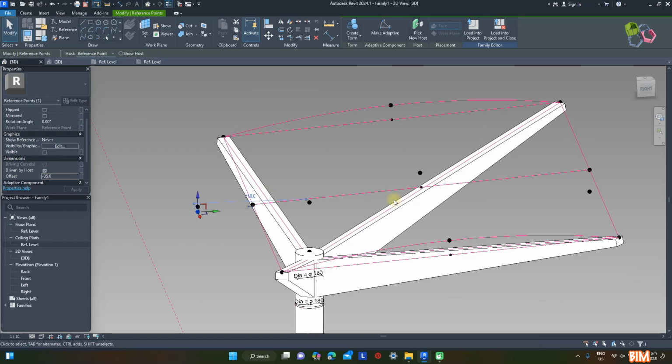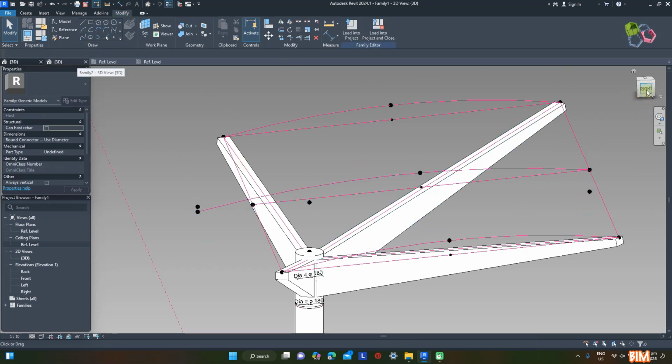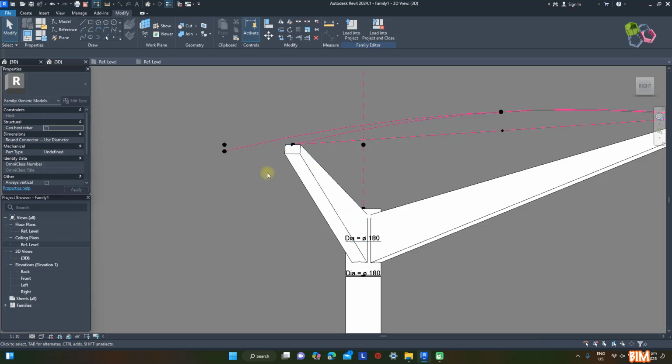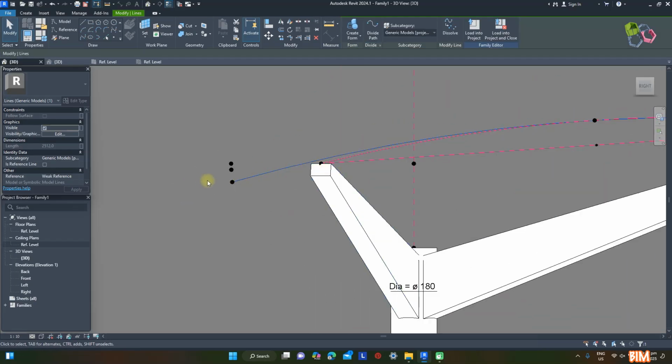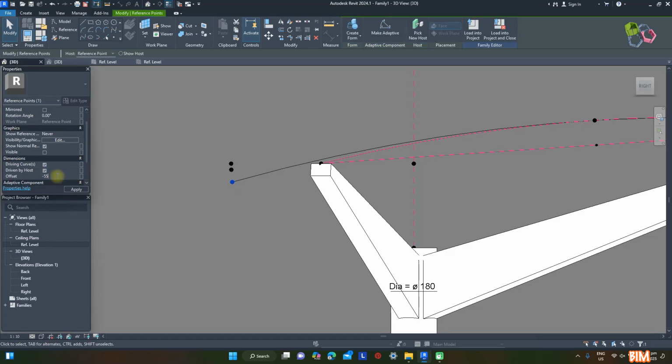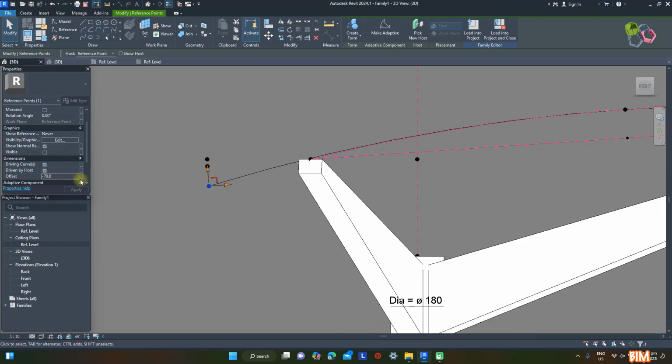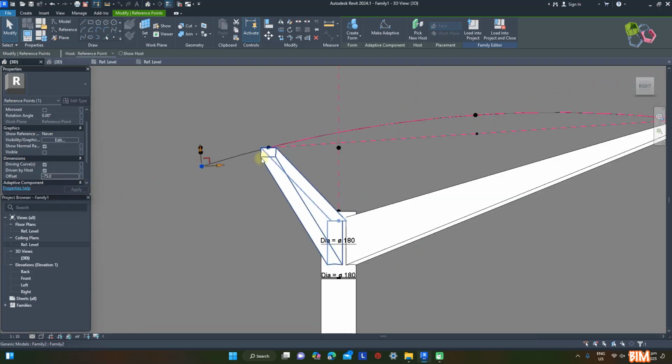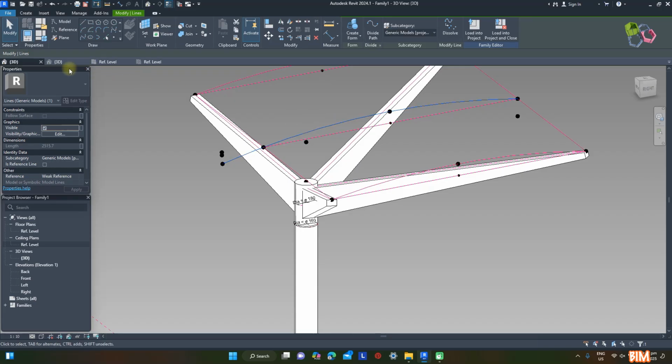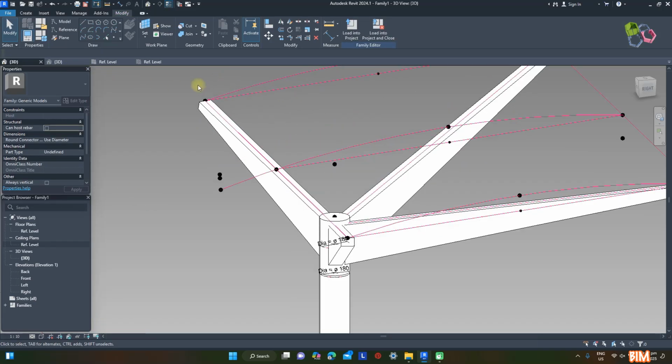This dropped offset is matched to the roof's curved form through trial and error. Adjusting this offset lowering by -35, -85, -65, -75 mm will be a perfect fit for the curvature. Some adjustment to make for the back curvature shape.